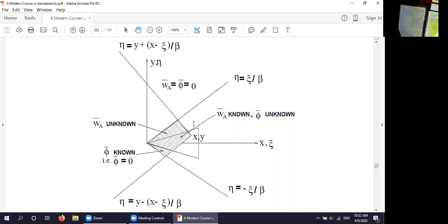If we are in subsonic flow, all these wonderful properties of supersonic flow are not available to us. What does that mean? That means that the flow ahead of this airfoil is disturbed. Why? Because if I oscillate this wing, a disturbance moves with the speed of sound, and if this wing is flying at less than the speed of sound, that means the disturbance is propagating ahead of the wing faster than the wing is flying.